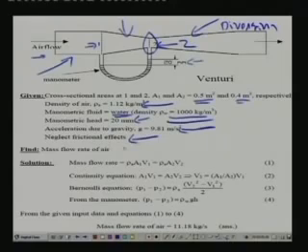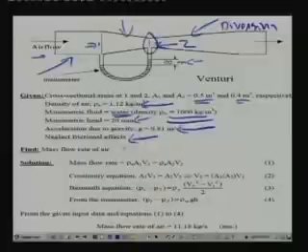and we can neglect all frictional effects. That means we will be applying the original Bernoulli equation, because we are assuming the fluid to be incompressible, steady, irrotational and inviscid. So, frictional effects need not be considered. So, if you apply Bernoulli equation, let us see what happens.